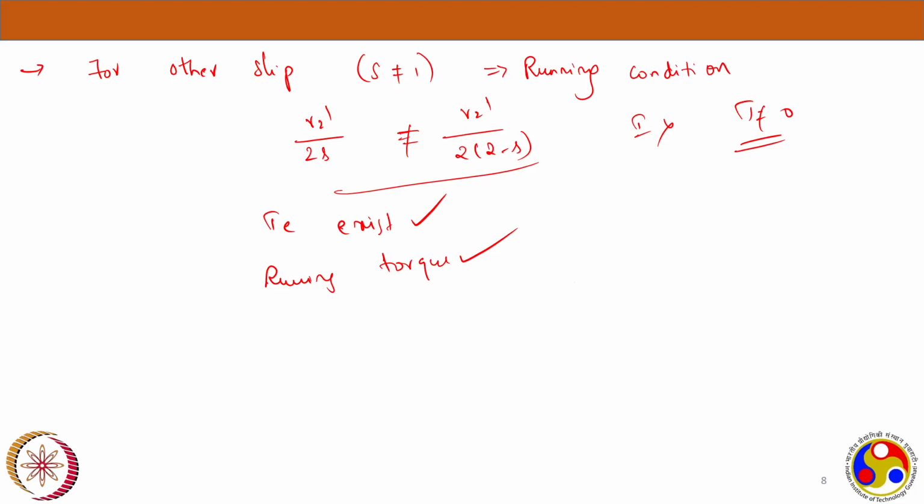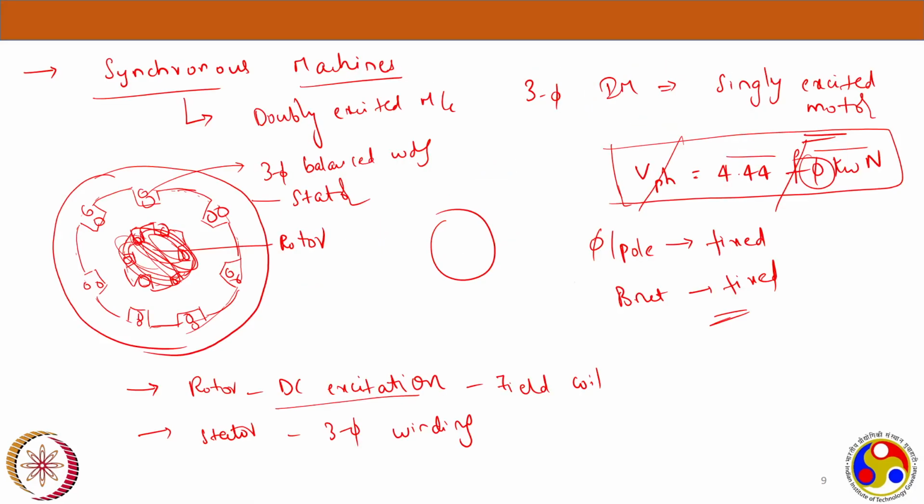Then we closed the single phase induction machine discussion, and we proceeded to the synchronous machines, which are very easy machines compared to the rest of the machines, but they need some basic concepts to be remembered. We started with the basic differences between the induction machine and the synchronous machine. A synchronous machine is doubly excited, having a DC winding on the rotor excited by a DC source. That way we generate two fields, one stationary and one rotating. So there is a need to rotate the rotor field as well in order to get a rotating movement in the machine.